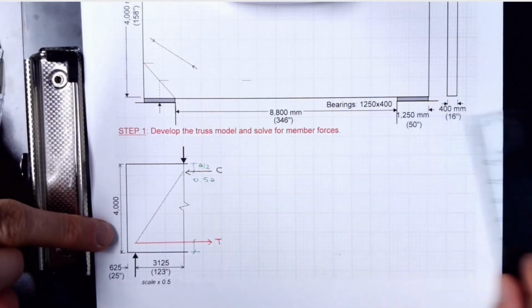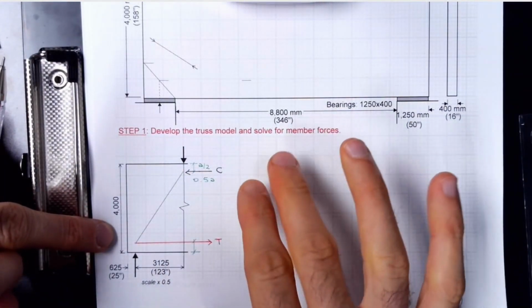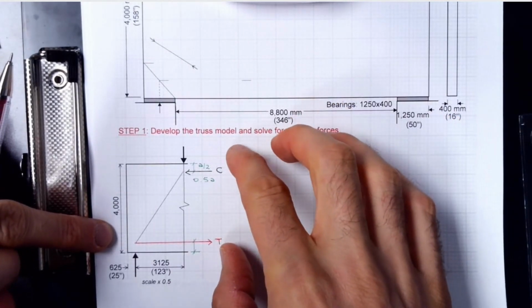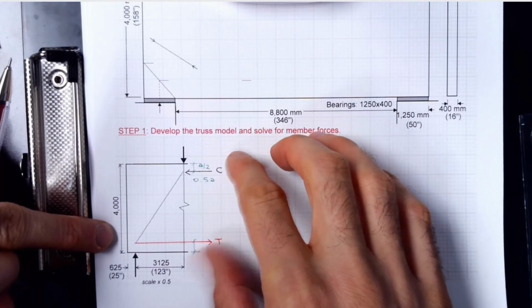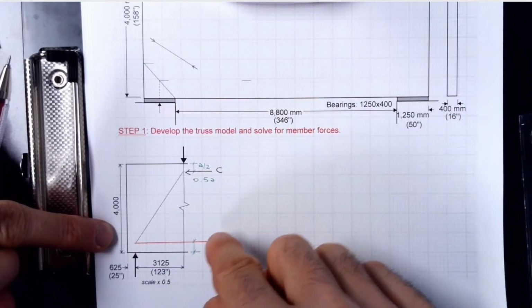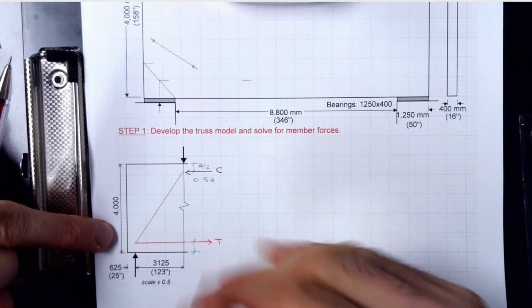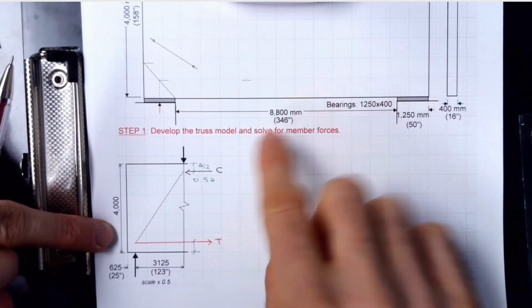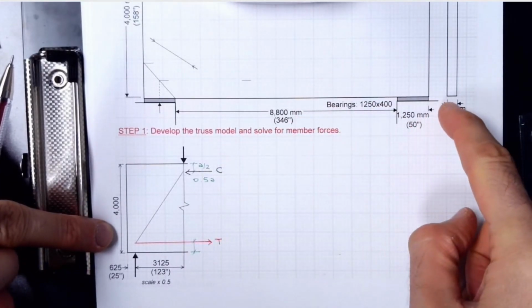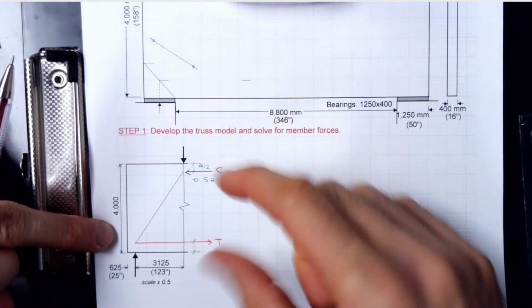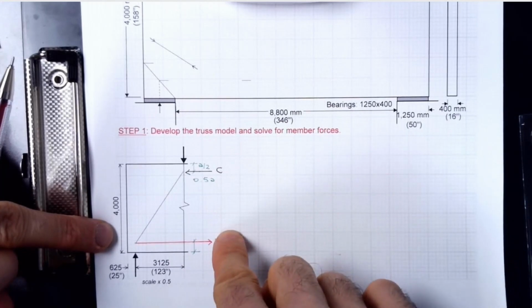There is really no exact approach to get started. You can make an assumption and start. You might assume 200, you might start. It's definitely going to be larger than 100. The forces are huge, the section is pretty narrow, so it would require more thickness, more depth for the strut as well as the tie.